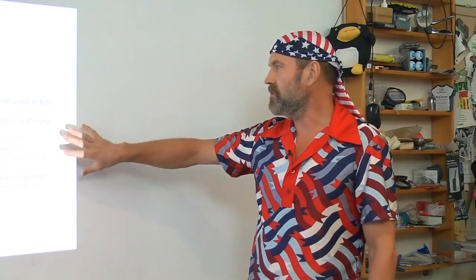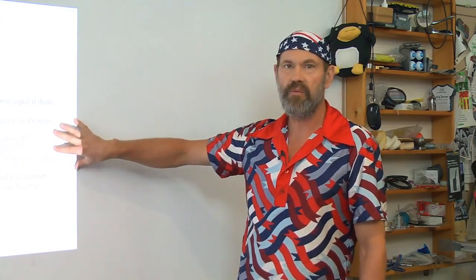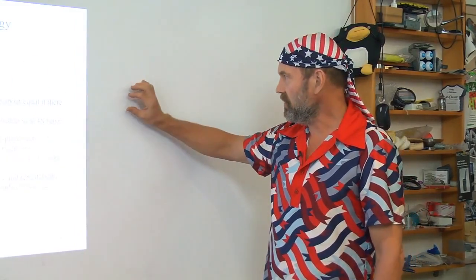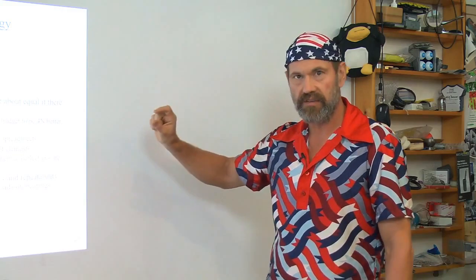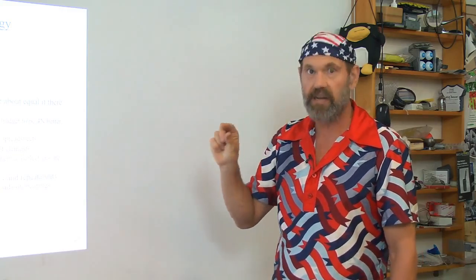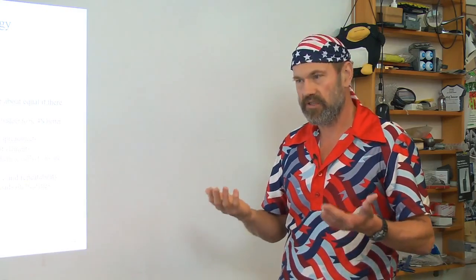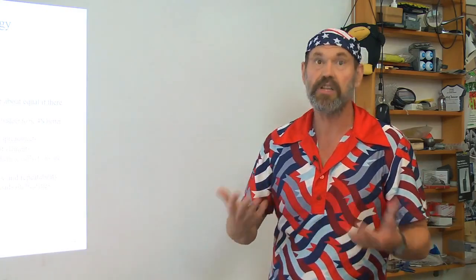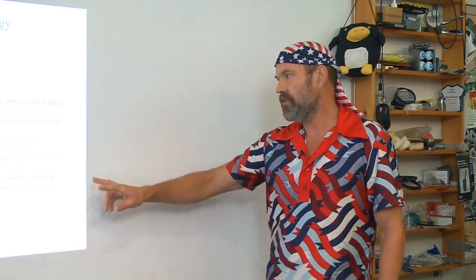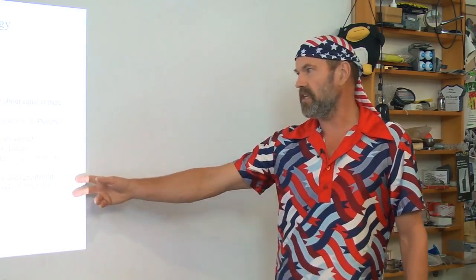During our concept phase, we're going to focus on geometric errors, and you'll see in a minute how we actually can design an entire machine just looking at the geometric-based errors. We're going to do that by apportioning the different amounts of error to the total allowable for the machine, such that if you design for the geometric errors, you then will have a starting basis to accommodate the other types of errors. The error budgets are only useful for predicting accuracy and repeatability of a machine, depending on which types of error inputs you define.